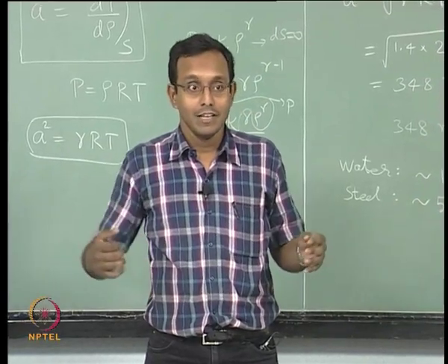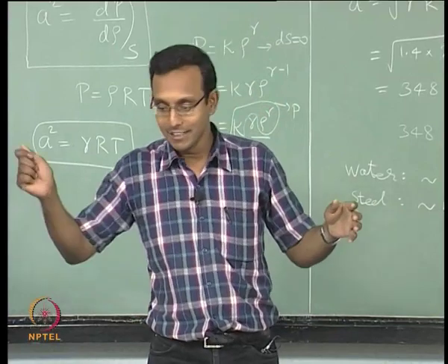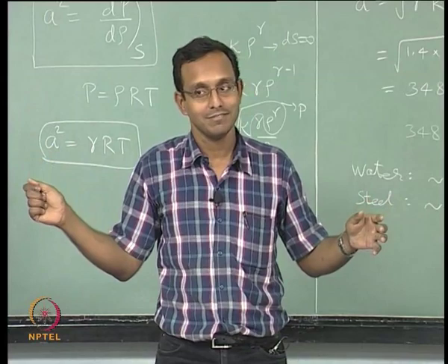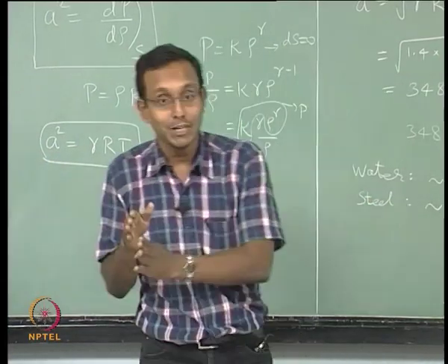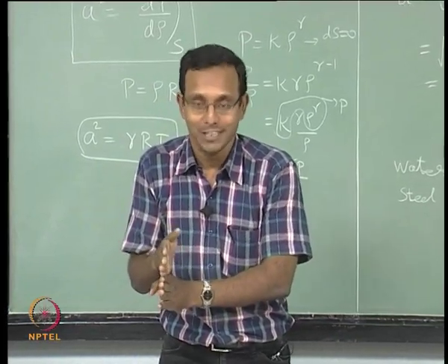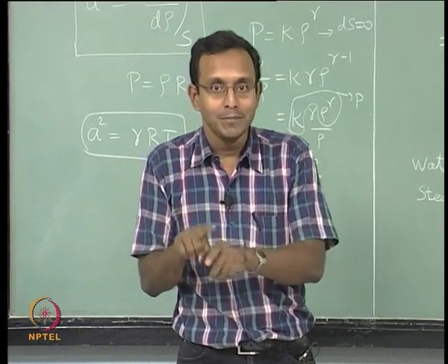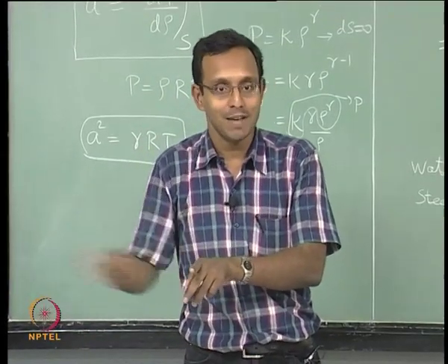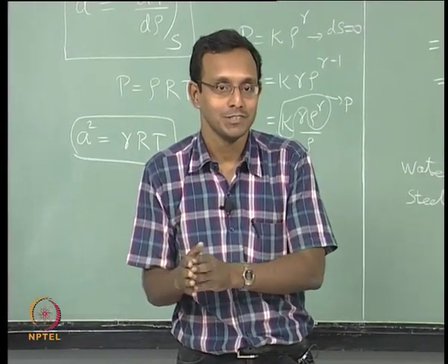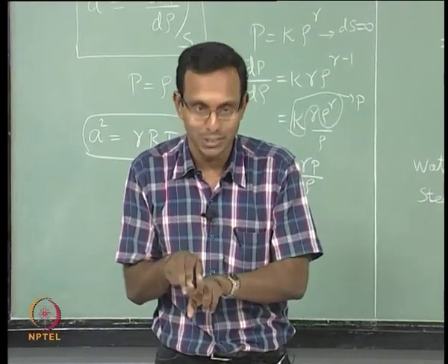If I keep on pressing with the hammer continuously, then this will happen, but I hit it once and took my hammer away. What does that mean? Now I am actually sending two waves. One wave is telling stress here has suddenly increased, right, that wave is going through. Immediately following that, I am also telling hammer is removed, that is stress has decreased. That is the next information I am sending through this. So I am not sending just one wave, I am sending two waves just next to each other.